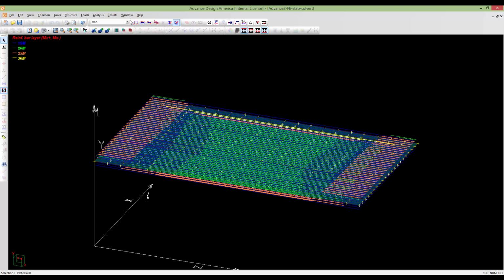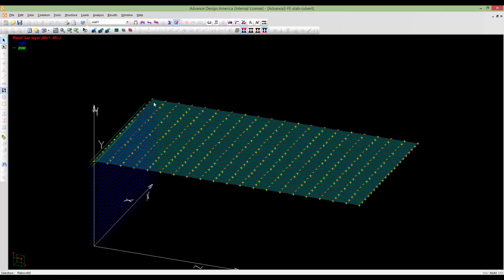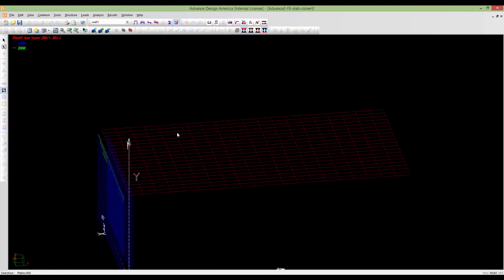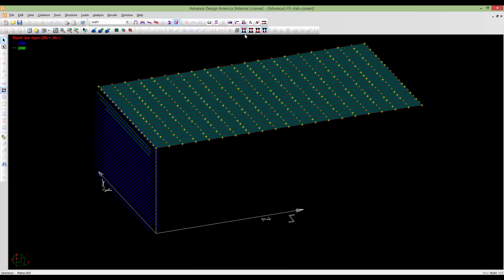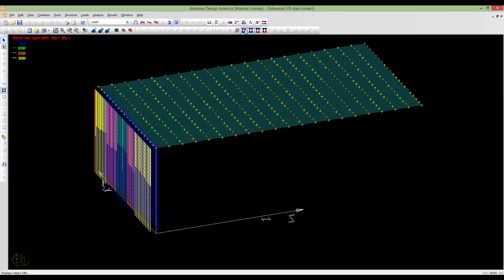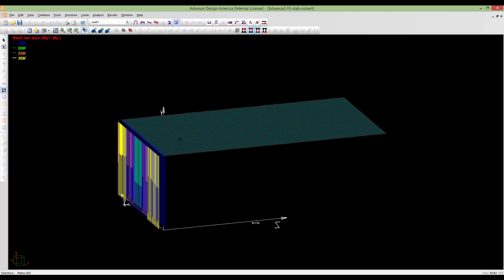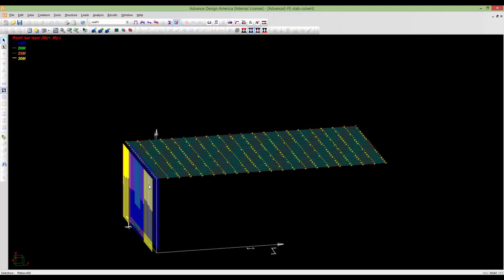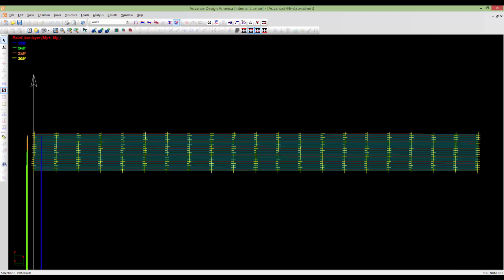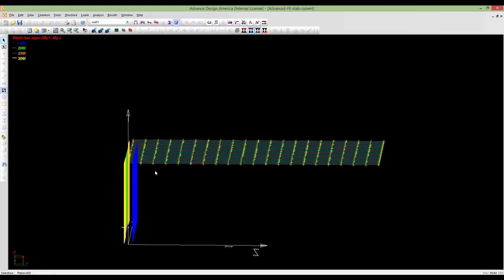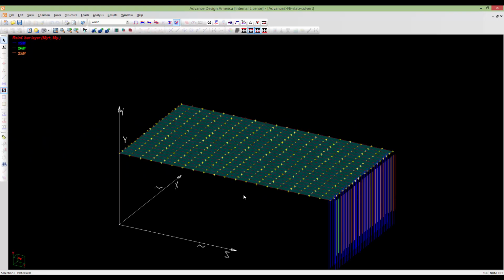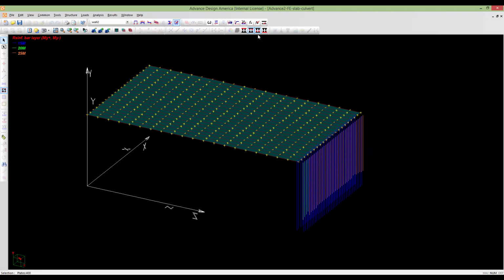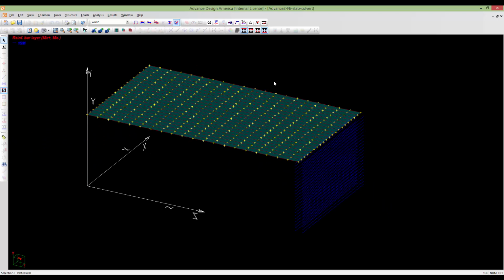And also if you want to check the reinforcement for the wall, you can just click here. You have these top and bottom layers here, 15 Ms and 20 Ms, and you can have the other direction. As you see, we have much more reinforcement here because of the moment on external face. And you have the results also for the wall too. Both directions.